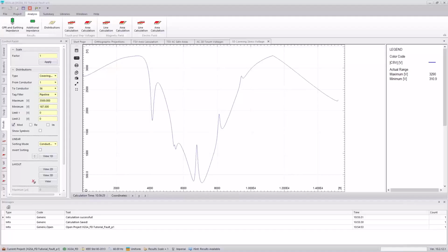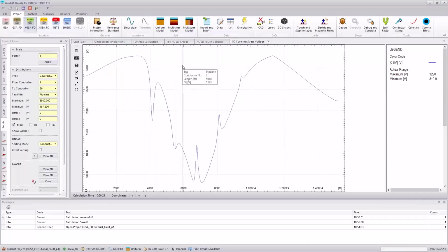Often you'll end up puncturing that flange with the amount of voltage you induce or conduct to a pipeline. So there are other types of insulating joints that have a higher threshold, or you might go to some sort of solid state decoupler to shunt around that. If you do have an insulated joint that is able to withstand the voltage that you're inducing on there, you can have conducted voltage through your medium, like your water. So you may need to increase that length, because you may think that you're isolating one portion of the pipe from another, but really it's going through that medium.